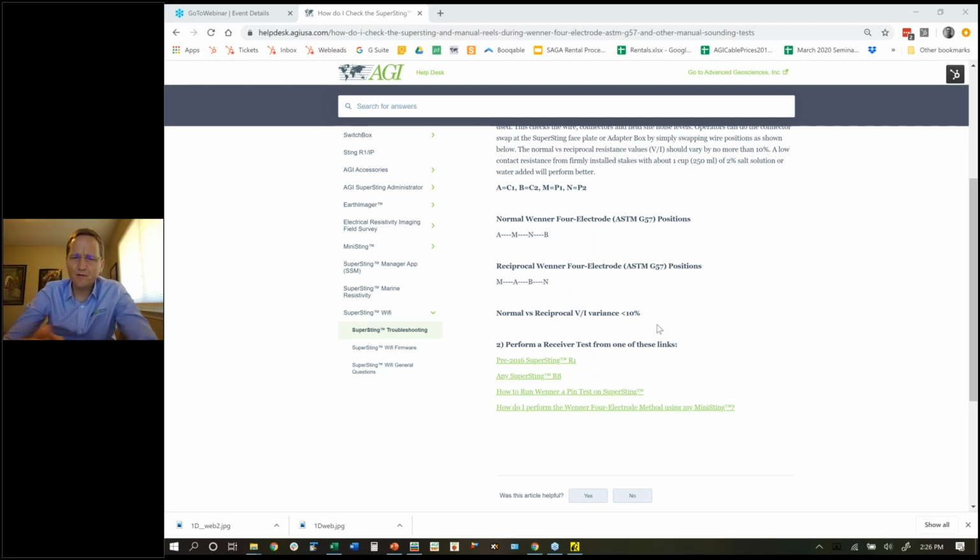There was a question about radial Wenner. It is a 1D method still, so you have those issues that I mentioned, but it can give you some anisotropy, but it won't let you know if you have heterogeneity. So radial soundings are still an issue there. It's best to do a 3D survey if you're interested in fracture direction and things like those.